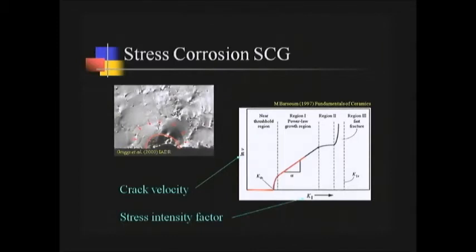we see that that increases the stress intensity factor, even at constant stress, and that results in a faster rate of crack growth. And so the crack accelerates. It's a vicious cycle. And then it will grow a little bit larger. And eventually, when it reaches the size of the critical flaw, we will be at this critical stress intensity factor, K1C. And then all of a sudden, the crack goes from growing at the rate of micrometers per month to meters per second, and you see failure of the restoration.